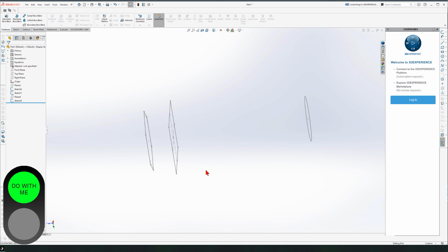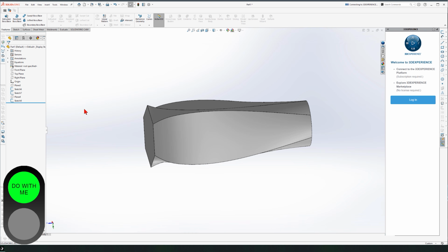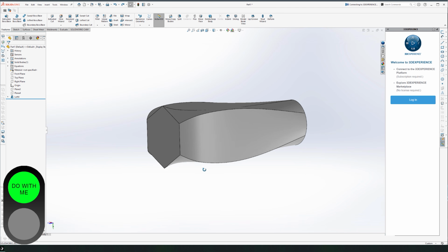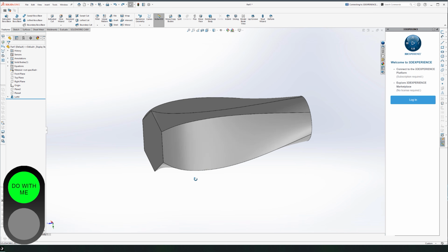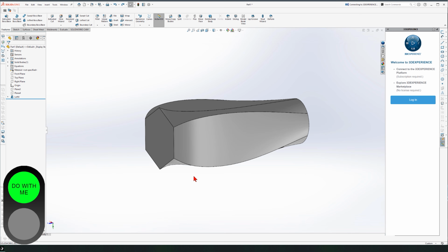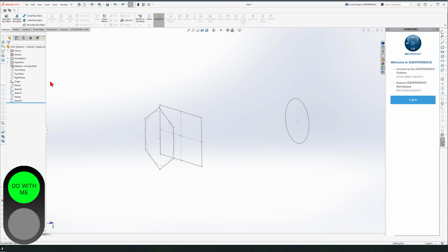We want to take it up a notch, as I said. I want to define the flow of the loft. Remember how our volume looks like? Just keep this volume in mind. I want to put it on the corner of the screen. And I want to delete this, okay? So next, we would like to pick another plane that cuts these profiles in half, like this one or this one. I'm going to pick this one, right plane.